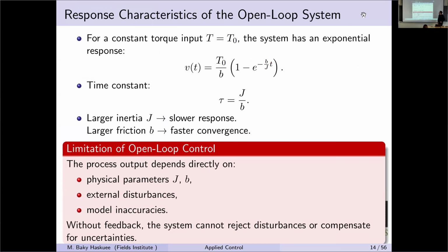So then the velocity will be set given the torque of the motor. You know that here there was the voltage set by the controller and sent to the motor. The motor voltage sets the current. I take the current as exogenous in the last equation, which is that the torque of the motor is a constant times the current. So given that we have the constant torque T0, the system has the expected velocity, the response velocity of the disk, that you can solve for.